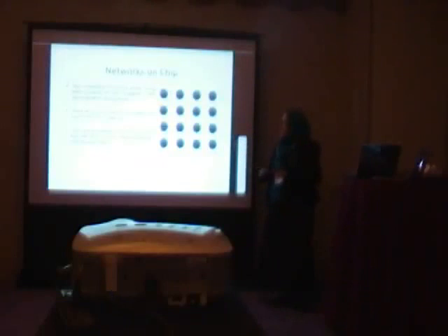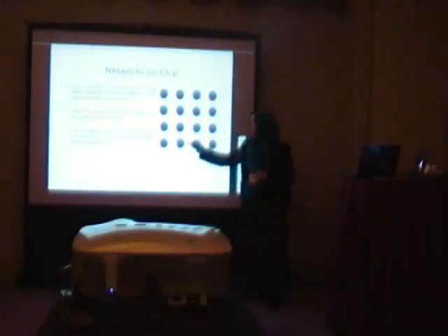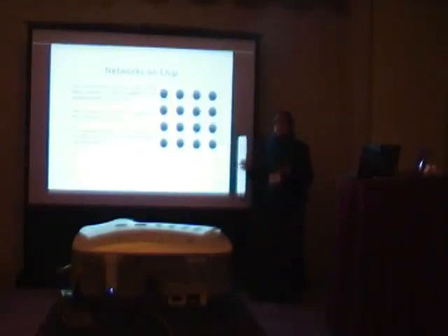You all know about network on chip, and it's the optimum solution for its optimized electrical properties. There are several topologies used: torus, mesh, stars. In our work we use mesh. In this topology, here is the link. Here we focus on studying the variability effect on the links. Circles represent switches. We don't study the variability effect on switches in this work.